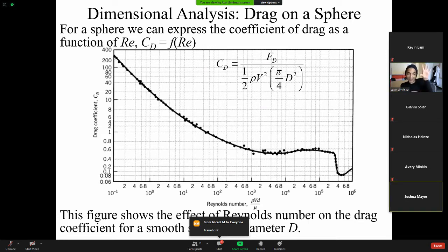So it's laminar. So now it's transition to what? Turbulent. Yeah. So what we learned is if you have a bluff body, like a sphere, or it could be like a rectangular cross section, for bluff bodies, in general, you want turbulent flow for the boundary layer.